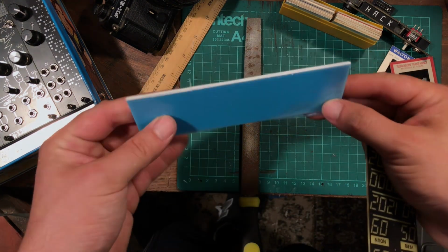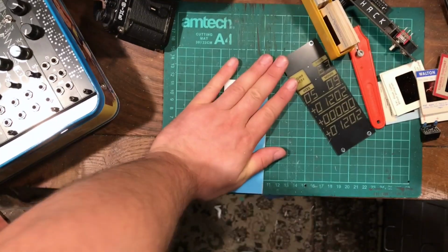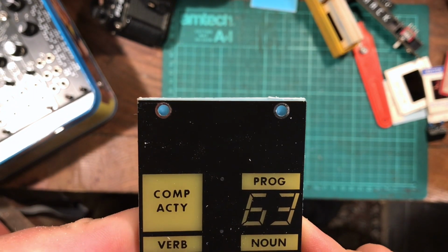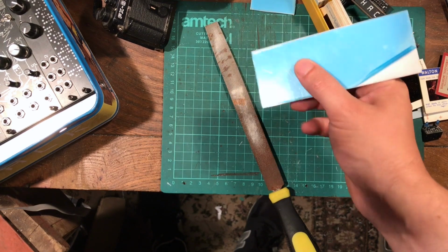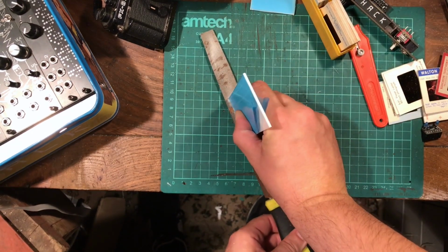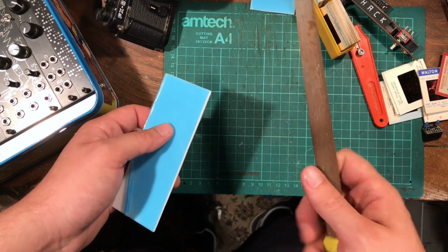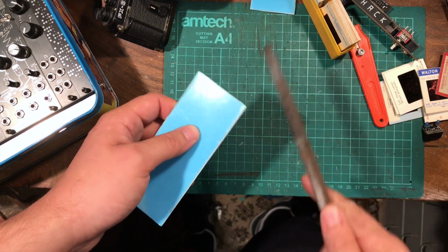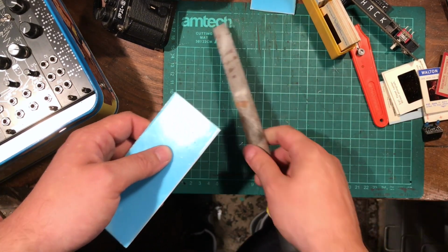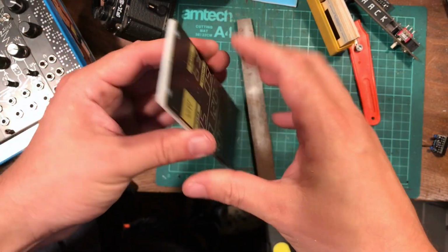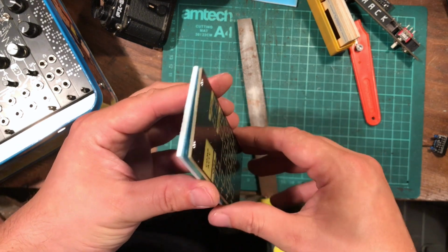Try and leave the film on for as long as possible. Oh yeah! See there? It's got a little lip at the top so I can file it down. And it really is best to hold the acrylic and press down flat on the edge against the file that's flat on the desk, because otherwise, just naturally, with holding the file, you'll start to round off the corners. Cool, so check it against your panel, make sure it's all good, make sure the edges look nice.